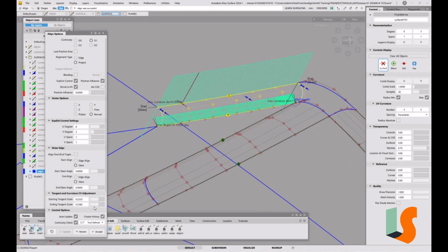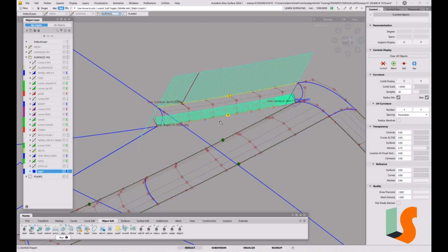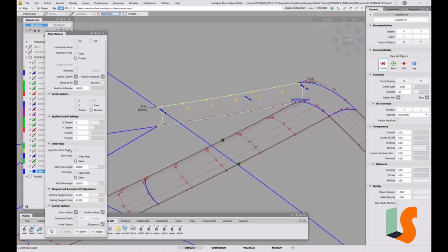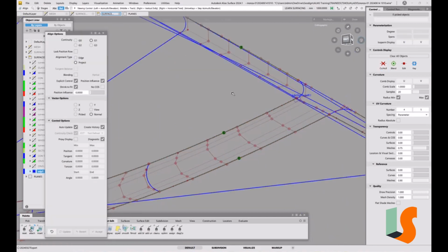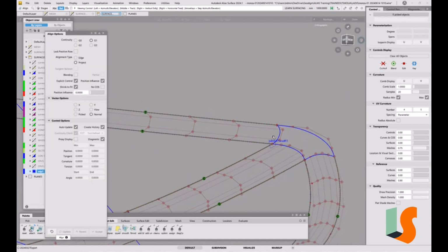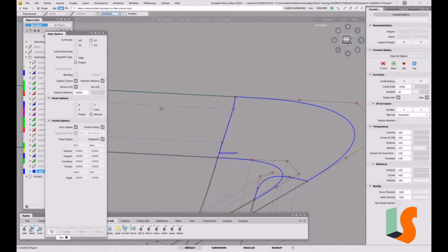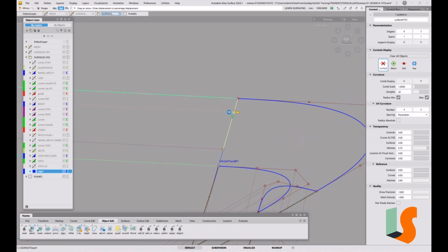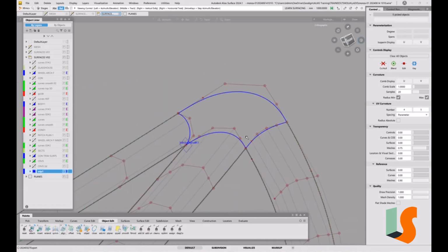So that's G1. Obviously, we can only look at that in terms of G1. So I'll get rid of those locators because there's locators on top of locators there. It's very confusing. So let's continuity check, tangency. That's what we want. It's that edge, and I'll straighten that up. I can straighten that up as well. Let's have a look at that end. That looks a bit off, but I could cheat and just do this, where I just slide that point along, just visually, straight enough.